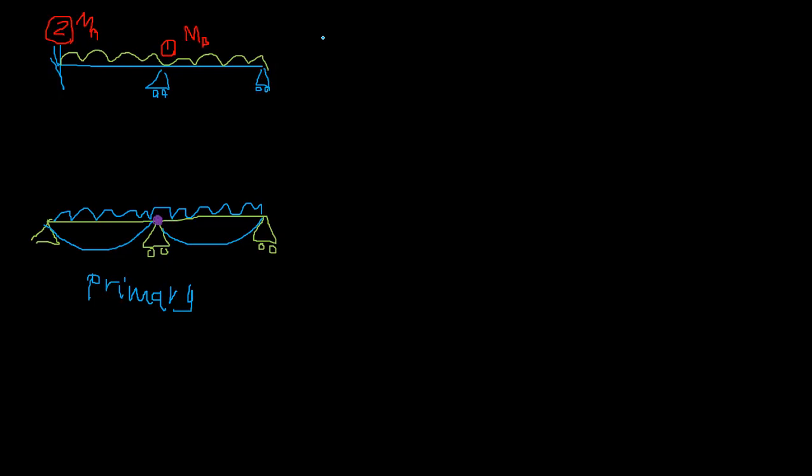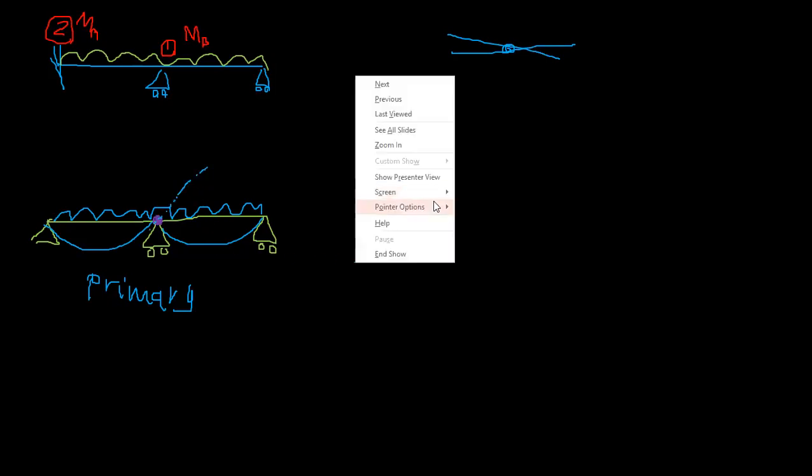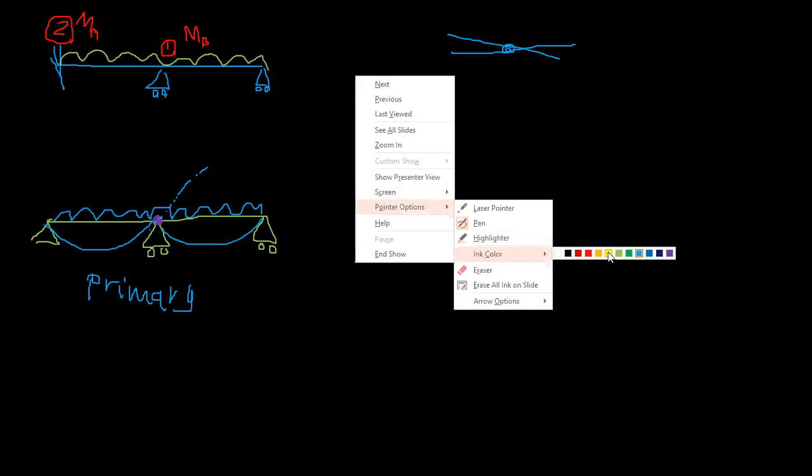Actually it's continuous. So you remember the relative rotation. If it is continuous, relative rotation was 0, right? Beam is always continuous. But with a hinge, there's a relative rotation, right? So you always consider this part. So that means compared to this, you should consider how much this has relatively rotated,